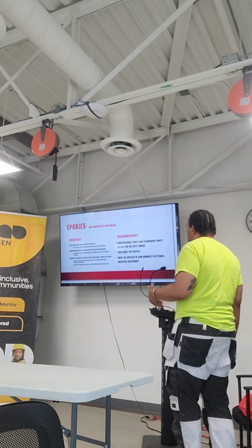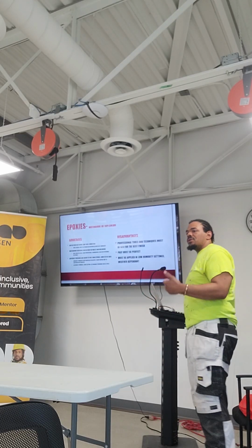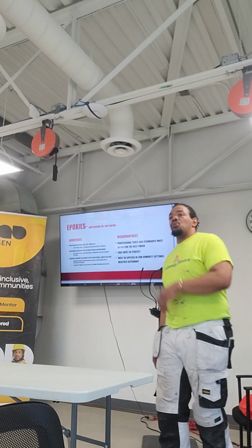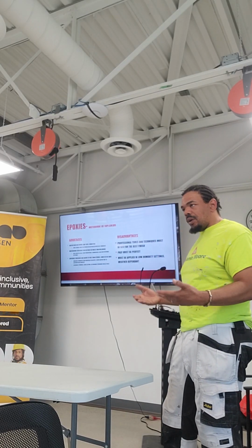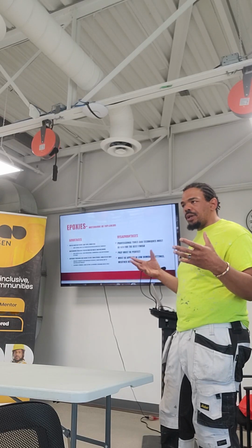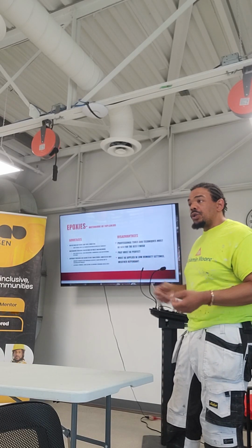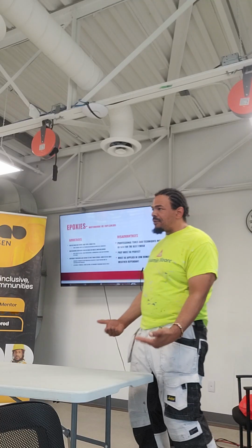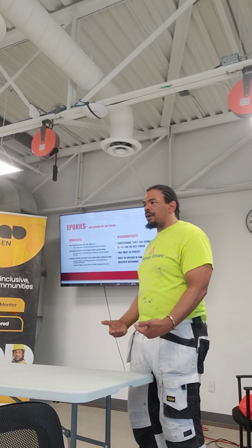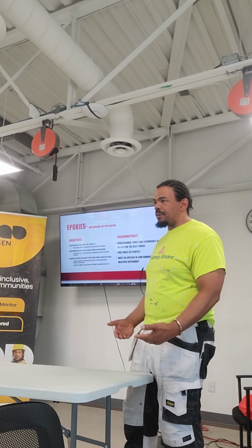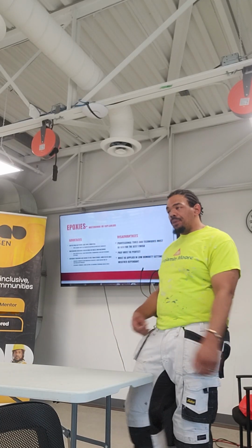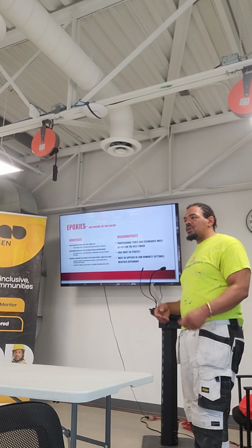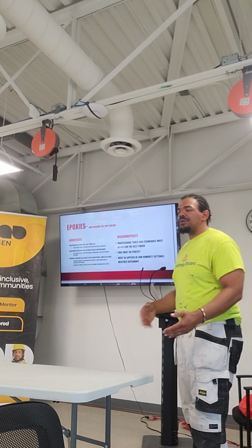But in any case, the epoxy has to be done in certain temperature settings. If it's way too humid, the humidity will sit. Humidity is water in the air, it's moisture in the air. So humidity will sit on top of the epoxy and it will prevent it from drying correctly. It will affect the curing time. You'll see bubbles, right? So you have to take a blowtorch and blow it out, or you have to use a spiked roller and roll it out to eliminate some of that.